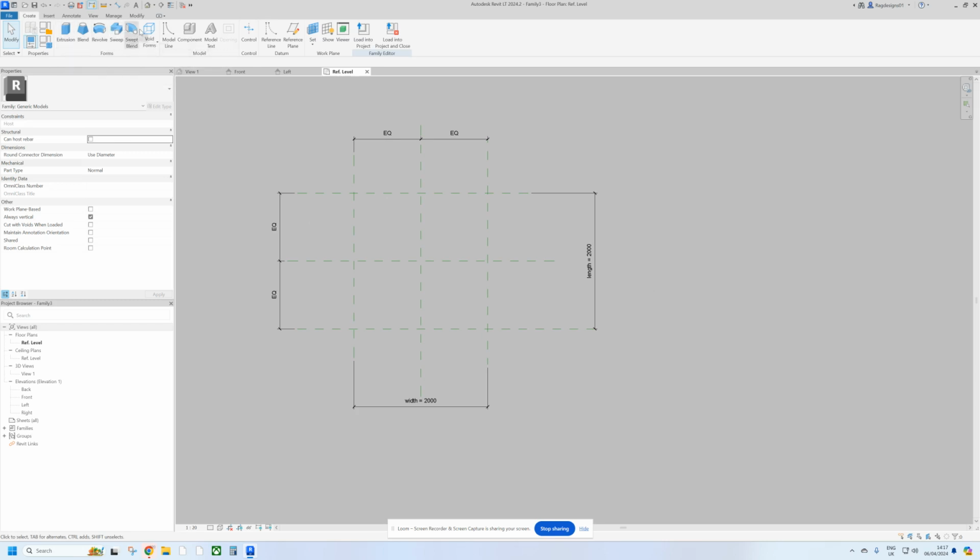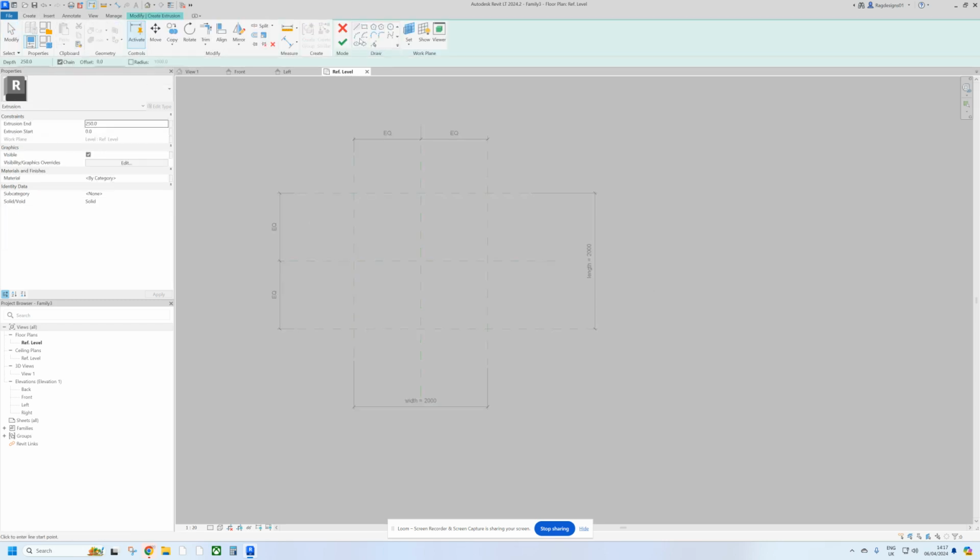There's a bunch of different ones here, which today we'll just look at extrusion, which is kind of the foundation one really. Now you could draw this as 4 separate lines for the box shape, but we'll use the rectangle tool. And if you go up to that corner there where it goes pink, and then click down to the bottom right one to the other intersection.